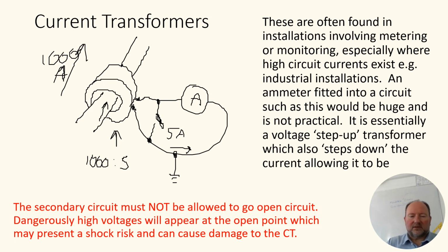So for that reason, a lot of CTs have provision to short out the output of the current transformer in order to maintain a low resistance circuit through it, while allowing you to carry out the maintenance on your ammeter. So you mustn't leave a current transformer open circuit.